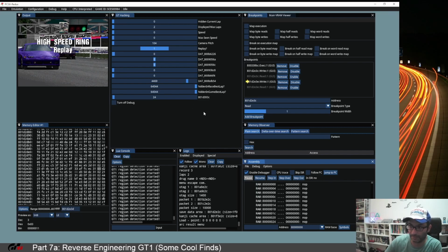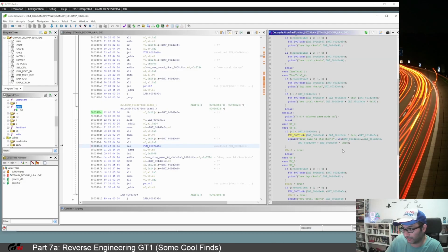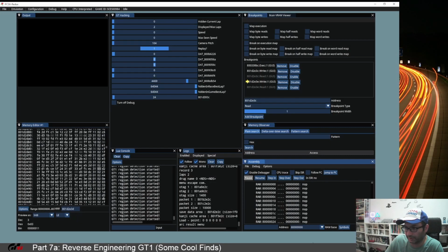So it's about to write to address 3E, and address 3E corresponds to this variable which should be greater than -1. I don't know if this is the reason, but at address 3E, it's currently D2. When I step in, I think it will become 3 or 5.